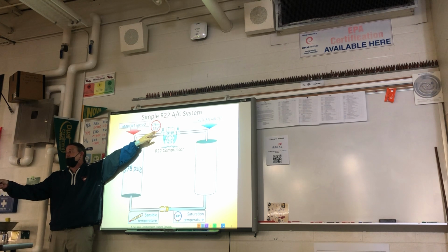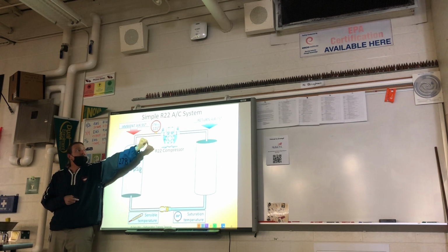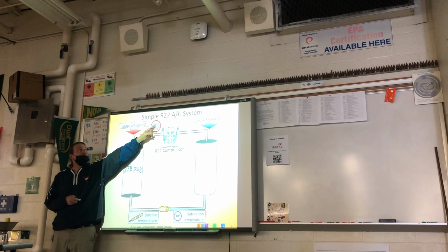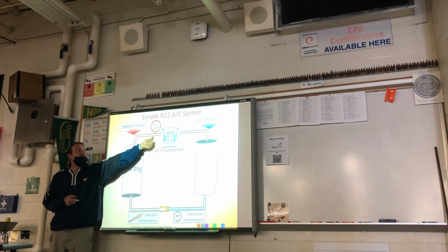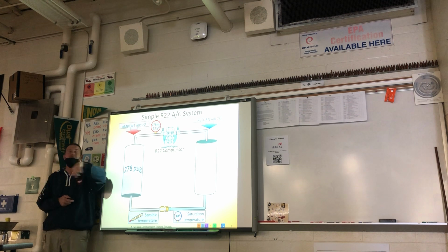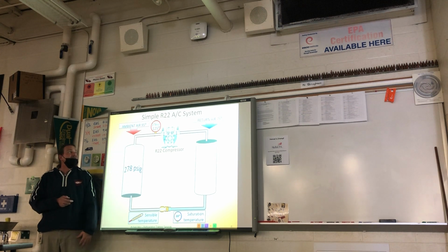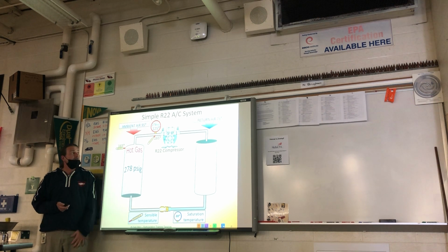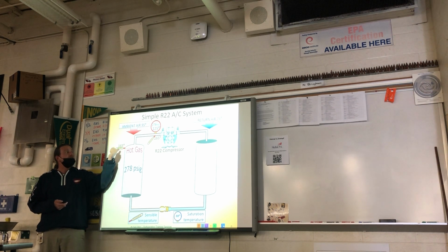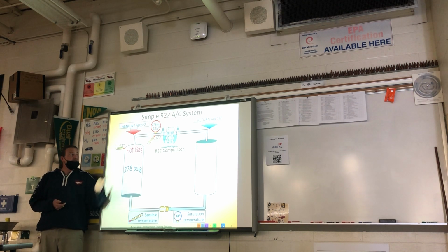And that's not where we say 125 degrees here. So I got 125 degrees here, but that is my temperature related to this pressure. That's not the actual temperature of the gas coming out. You felt that when you ran that unit for a while and touched this line coming out, that it could have been 165, 175 degrees, right? You can't hold on to it for too long. So the first thing the condenser has to do, it has to de-superheat that hot gas.